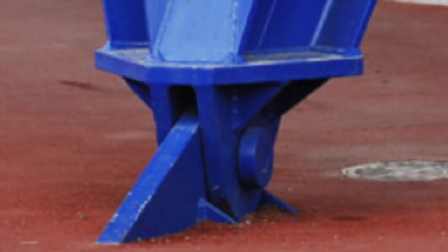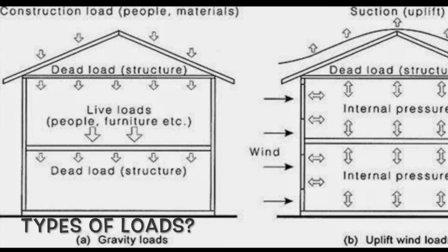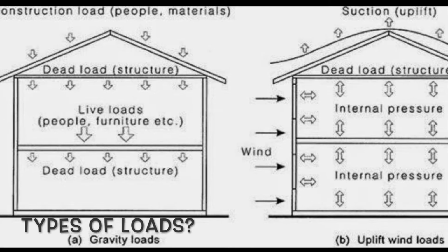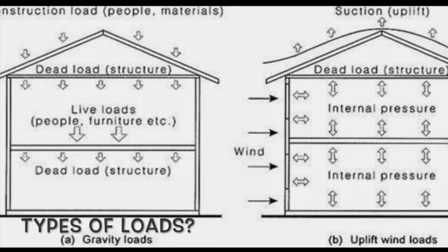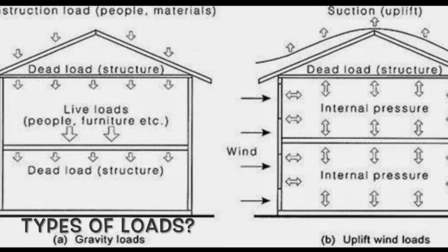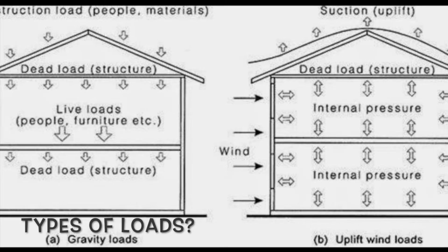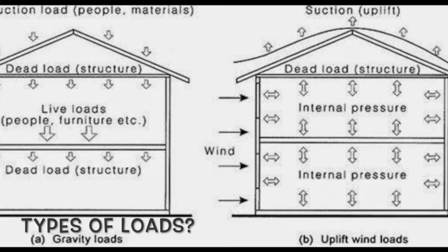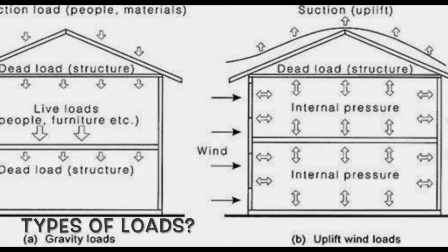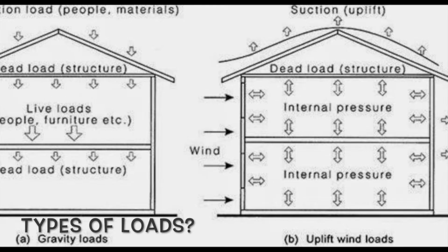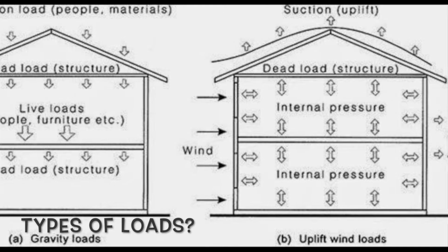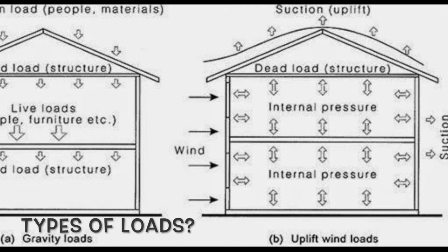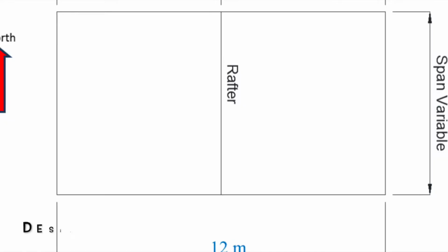On top of the members, the loads applied are also a great factor. On a commercial or industrial building, live loads, dead loads and wind loads are most commonly present. Live loads change over time or are not permanently there. Dead loads are always present within the structure, mainly through the self-weight of members. And wind loads are affecting the structure in both pressure and suction, or positive and negative forces.